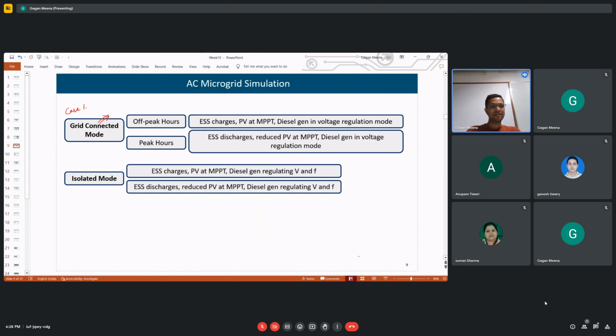First, it will try to maintain a constant voltage here, regulating this voltage. Then it will also vary this voltage so that these two impedances become equal to extract the maximum power.